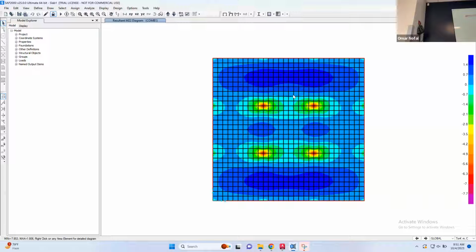So if I'm not depending on the beams to resist seismic, I can design the beam right now to only take the gravity load: the weight, the lights, the flooring, and everything. And I can design this system. However, if I'm going to do seismic analysis, this model is not enough. Seismic analysis needs a model for the entire building.